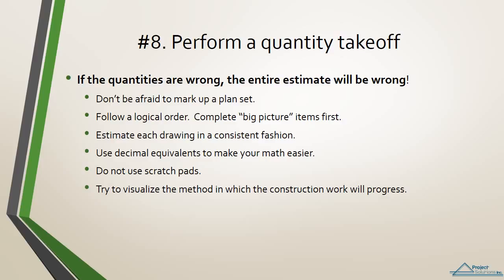Do not use scratch pads. You need to be able to review your work, and you should be performing your work in sufficient detail that a scratch pad shouldn't be needed for calculation purposes. Try to visualize the method in which the construction work will progress. This will help you discover items that may not be included on the plan set, such as finishing concrete, and will help you to determine other cost control elements, such as working room.